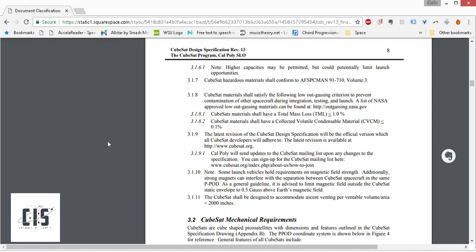Cadmium and zinc are especially bad on fasteners. A lot of fasteners have zinc coating. Oh, jeez. So that's why I'm getting all the black oxide, because that's the only other option on McMaster. Gotcha. I learned. We might have a whole section just dedicated to that, because that was really good. If you have wires, you've got to make sure the insulation on those wires doesn't outgas, because it might. This could either be a material turning to a vapor, or water that got trapped in it while it was in an atmosphere, and then it comes back out again when it's up in space.